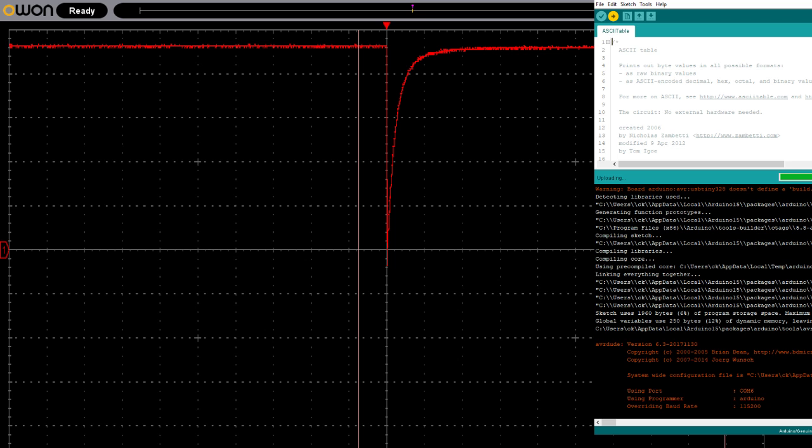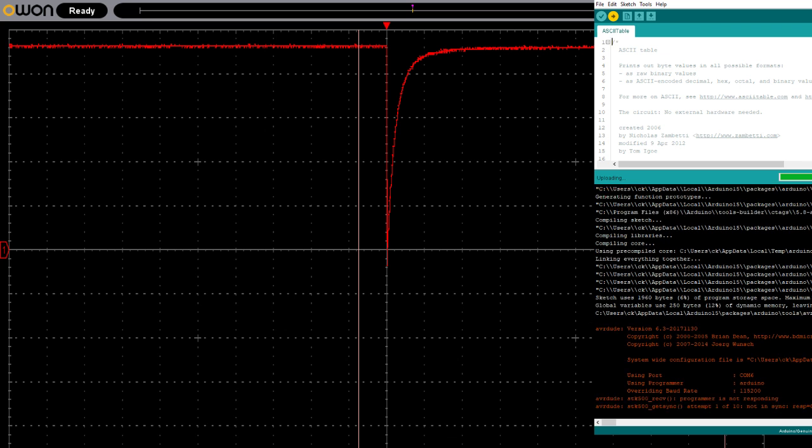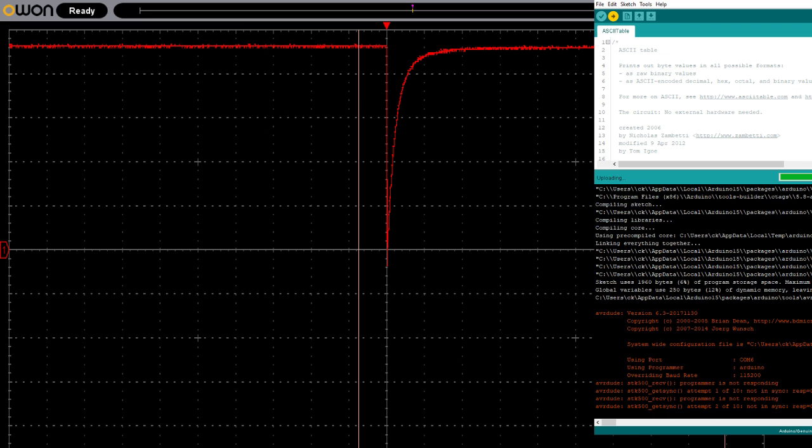so I've moved all of the wires that come off the FTDI to one pin offset on the breadboard, so I can literally put a little scope wire down between each pin and the breadboard. So these signals have to be reaching the chip, and the chip is definitely all the way pushed in. So double checking, that's the reset. Looks exactly the same.